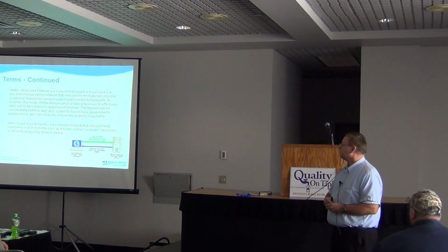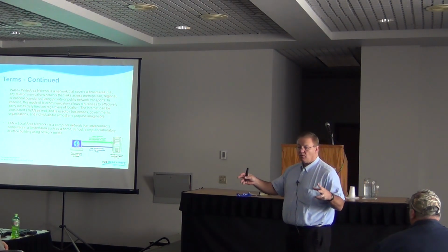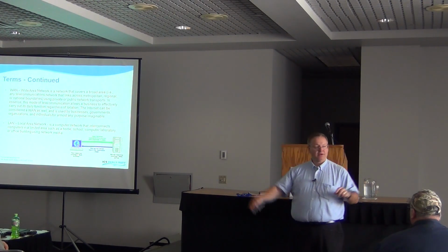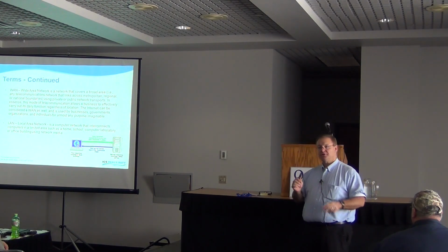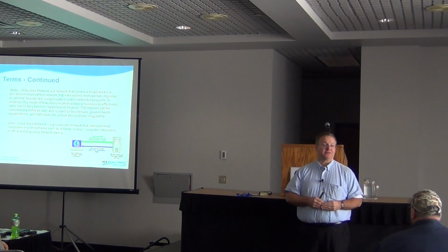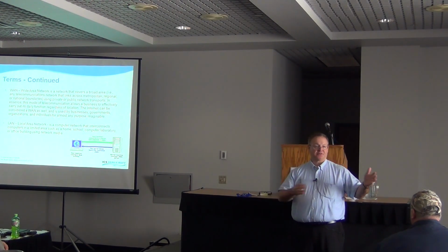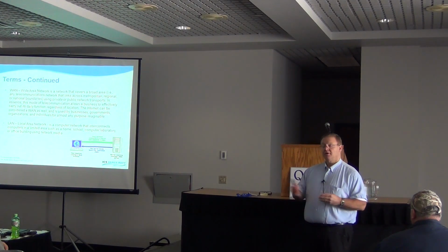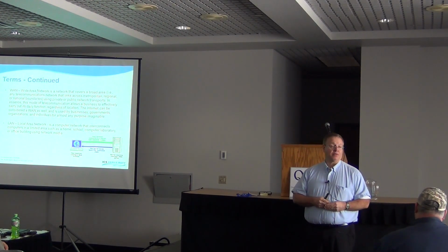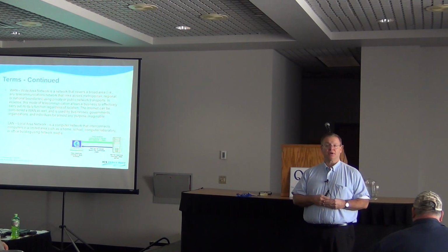Wide area network. You'll often hear this in telemetry and SCADA. Wide area networks are like in a water system. I've got a tank over here, I've got a well over there, a booster station here, and a plant over there. I'm going to use a wide area network in order to communicate all those things. So I've got to have a communications media that supports long distance. It could be lots of different things: radio, even fiber optics. Getting information to your home through the phone lines is basically wide area networking.